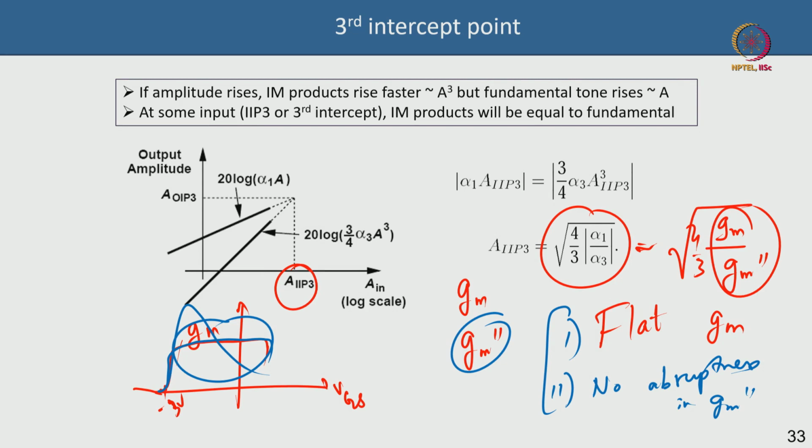There are also other aspects pertaining to the linearity of the device level. For instance, your capacitance CGS has a nonlinear dependence on the voltage, and gate drain capacitance also. So, those capacitances can vary nonlinearly. There are traps in the buffer of the gallium nitride, on the surface, on the interface, and those traps can behave non-linearly under large voltage swings. There is a heating effect also that can play a role in non-linearity, because the heating will raise the temperature and activate more traps. So there are different factors that also contribute to non-linearity.